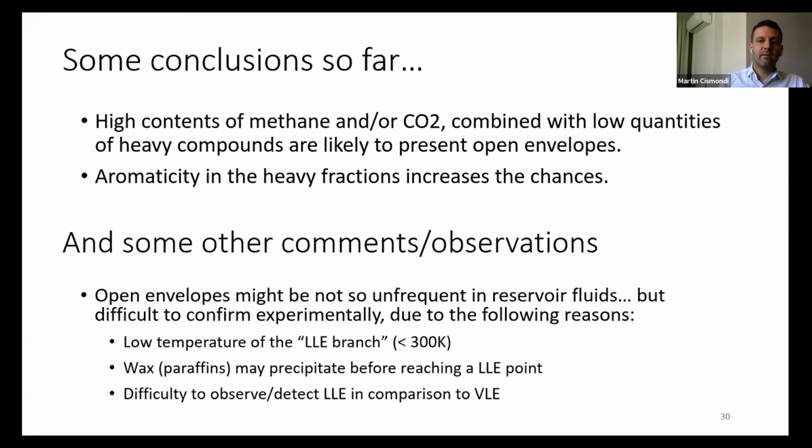And even if it's not like that, and you could in principle measure the liquid-liquid saturation point, it is difficult to observe or detect LLE saturation points in comparison to VLE. I think the experimentalists here can agree on that. And especially in reservoir fluids, in petroleum-like fluids, because of the darkness. So you have to resort to different experimental techniques to detect those points, which are not easy. So sometimes you may think you have only one liquid phase, but actually you have two, but it's difficult to detect.